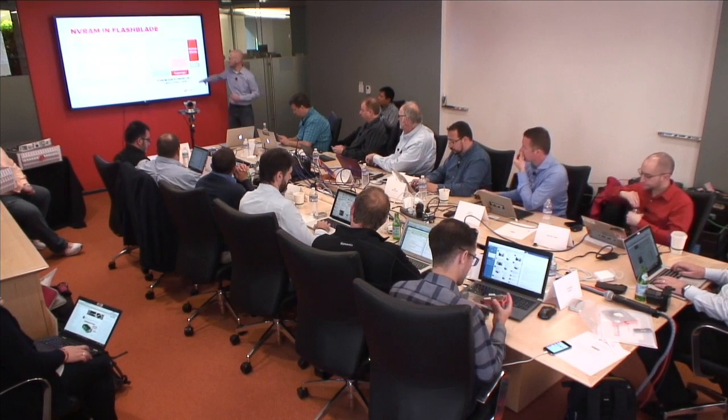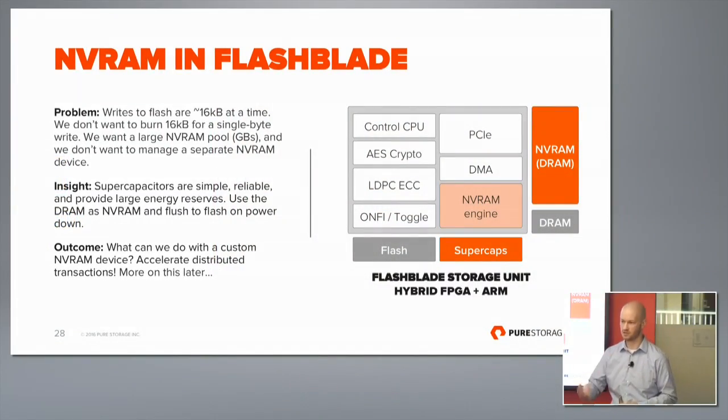So with a new flash technology, we're really adapting how we do encoding, somewhat how we do signaling, although that's fairly steady these days. And the rest of these blocks are fairly standard. The whole thing we've implemented in an FPGA, which gives us that adaptability. We're not doing a new silicon spin every generation. And so already, in our prototype phase, before we even go to full production, we're using 2 wildly different flash technologies for our different sizes.